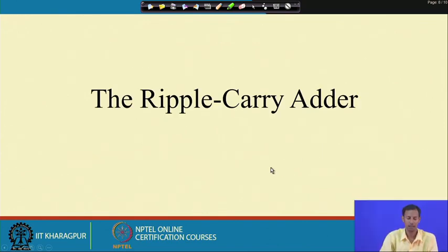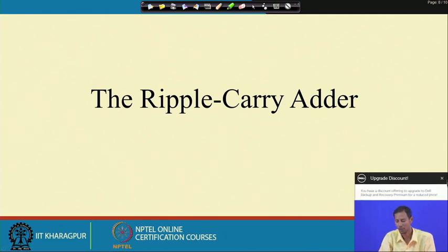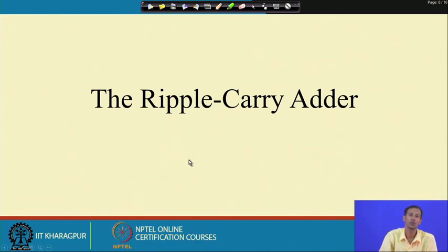After that, the ripple carry adder architecture comes. Why do I need this ripple carry adder? I need it whenever we are considering n bit numbers. Here we are doing only single bit addition, right. We have multiple bit operations, as you might know that present day computers have become 64 bit. Some of the cryptographic cores are 128 bit long.